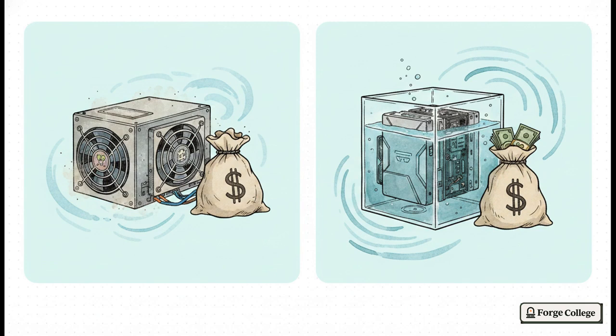So, let's look at configuration A. This uses a recent, but maybe not absolute top-of-the-line ASIC with traditional air cooling. It's giving us 70 watts per terahash, costs about $2,000 up front per machine, and has a PUE of around 1.15. Then, we look at configuration B, the absolute bleeding edge.